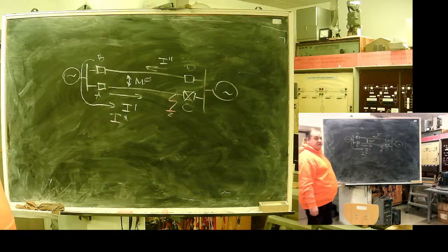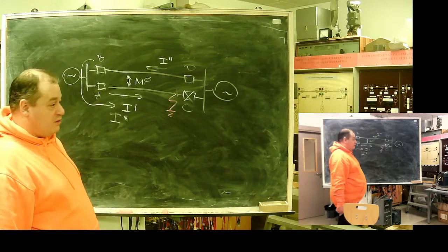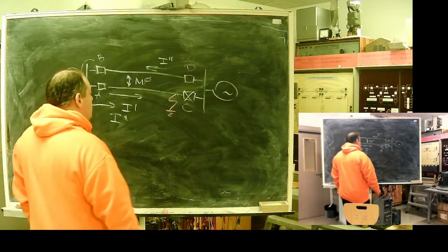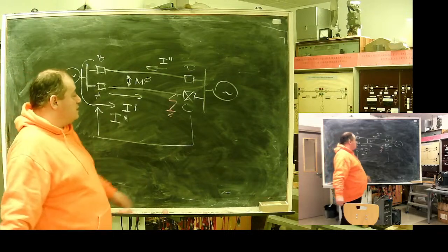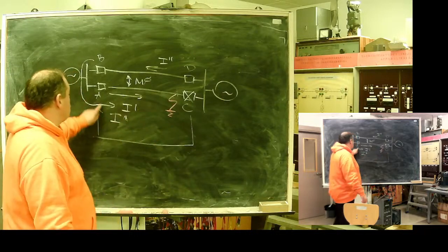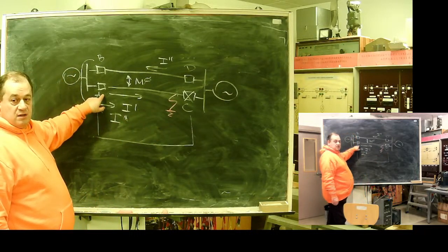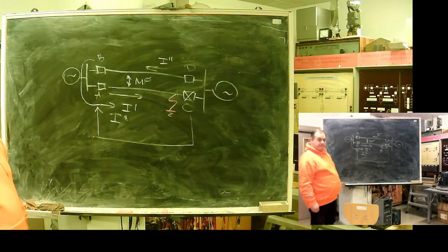If there is a communication channel, one thing is very helpful here. If you have communication network, trip signal from the far end should be sent to the opposite end instantly. It's good for system stability. It's good to decrease damage of the fault.